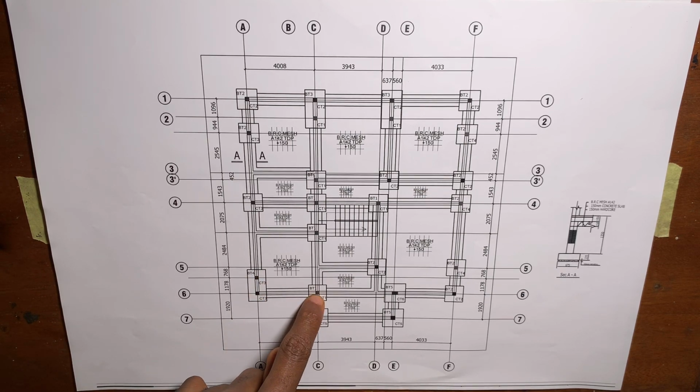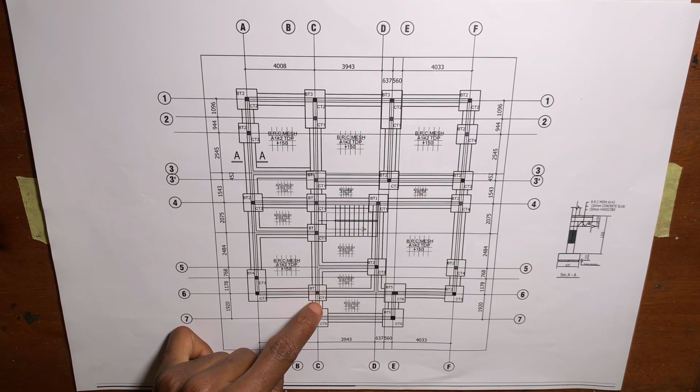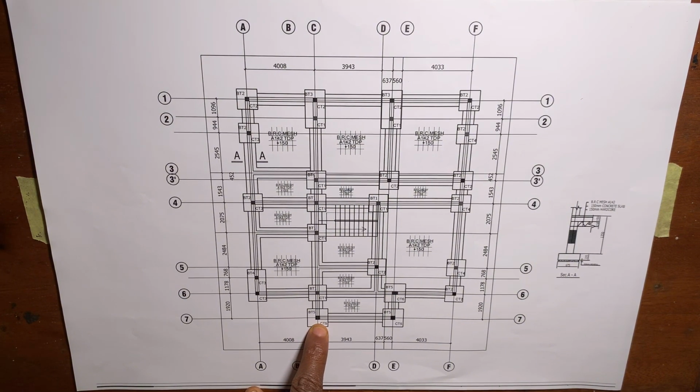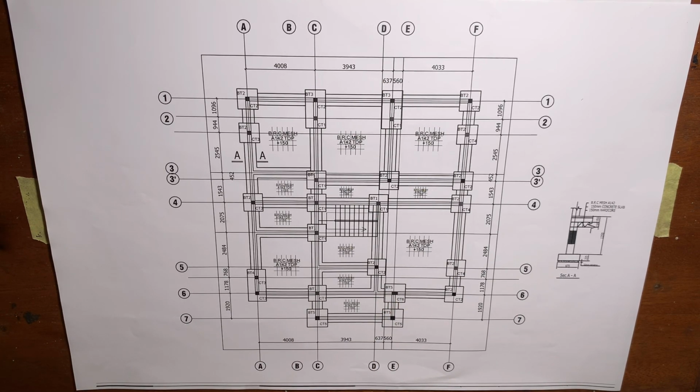The same thing applies to this, and this, and this. You can see that there's CT1, there's column type 5, there's column type 6, all having different shapes. If you look closely, this column type 1 is smaller than column type 5, but they are both square in shape. Column type 5 and column type 6 are different shapes. Column type 5 is square, column type 6 is rectangular. That is the reason why they had to differentiate the column bases and the column types, so that you can know that they are not the same.